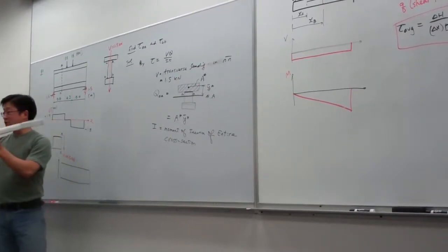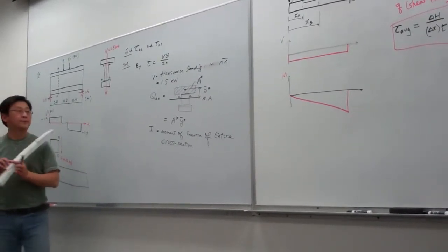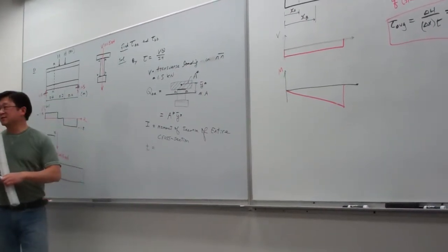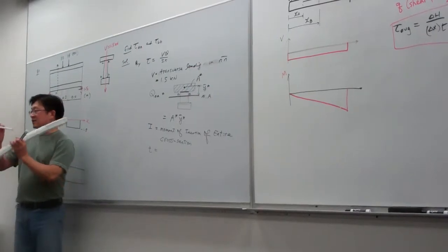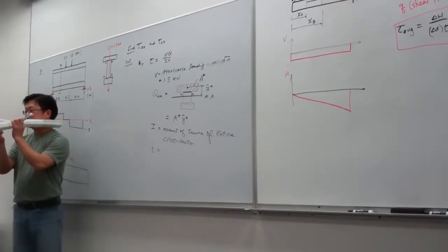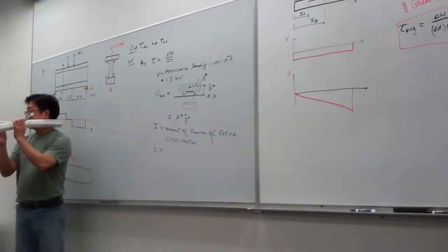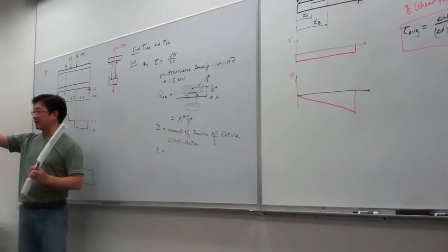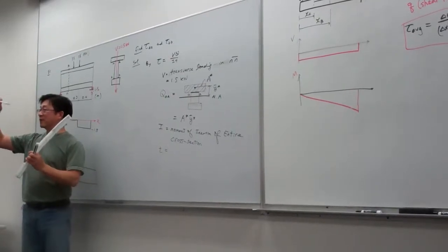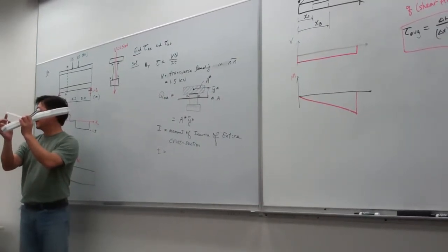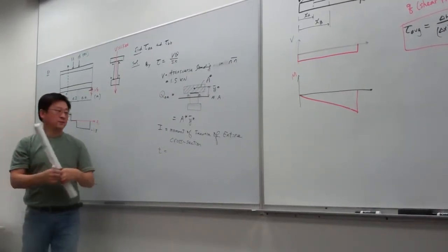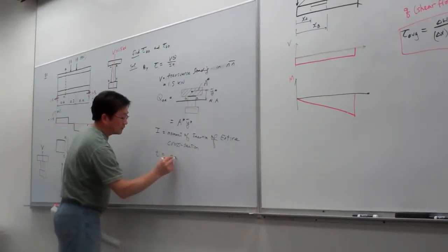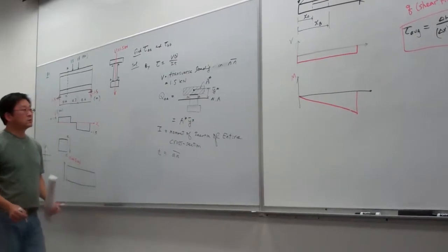Not the shaded one, no. And T is the thickness, where the thickness is at AA. Because we're going to calculate the average stress over this area, which is related to one dimension here, right? That is T. For this example it is the AA distance.